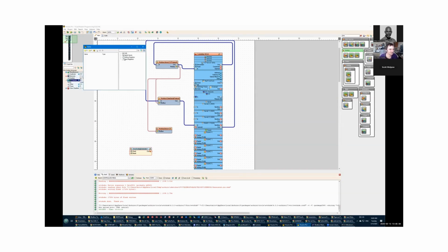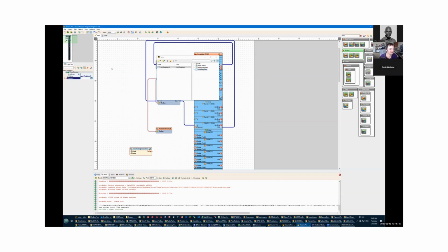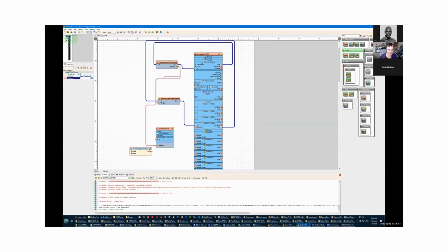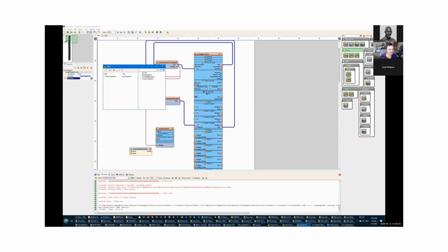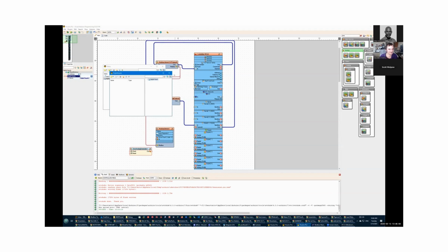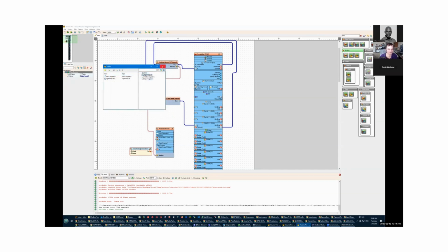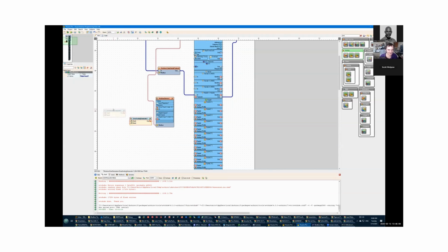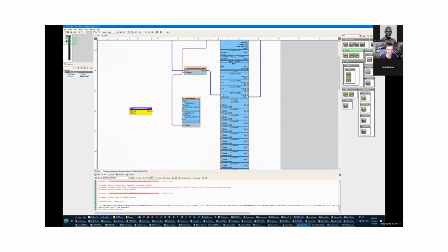And here we'll do something else. Yeah, let's do input register. Add one register. And I'll actually add one coil. Not coil, but digital input. So digital input table. Again, Modbus devices are a bit weird. They work in terms of tables and then elements in those tables. So that's how Modbus works. That's why I have to add the table, and then I have to add elements in the table. And the elements in the table are indexed.